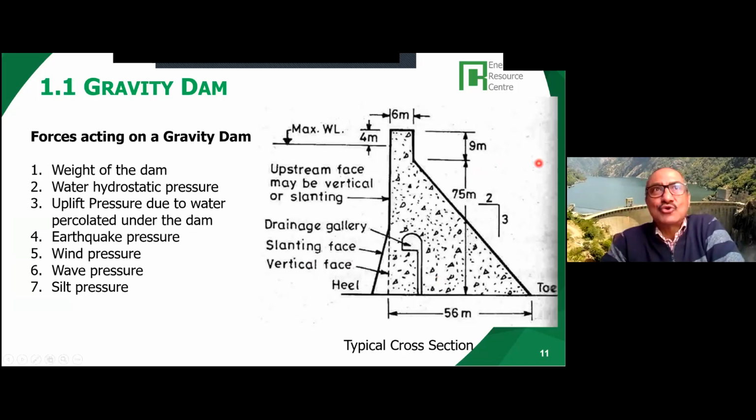Okay, now I will go into some design aspects. It's basically the hydraulic design aspects of a gravity dam, because it also helps you to design your weir. In a gravity dam, what a civil or hydraulic engineer has to do is hold this much water upstream basically by the weight of the dam. And this dam normally has this sort of typical cross section.